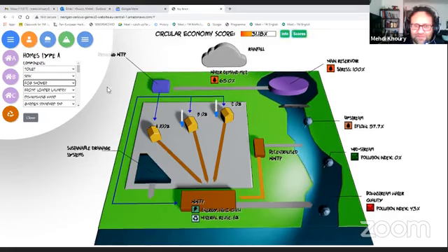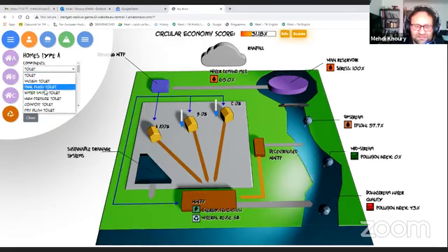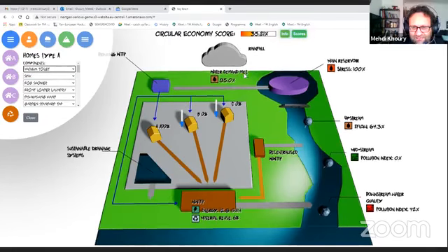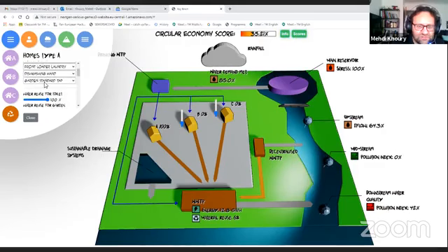Now, this is one thing we can do. Perhaps we can select in there what is the best possible toilet. I don't remember which one is the best toilet technology, but let's say we put in a vacuum toilet, which is fairly expensive. So it might make our score go down a bit on the financial side, but that saves water. So if I put in a vacuum toilet, I can see we now meet 85% of the water demand, and so on. So we can try different combinations of technologies.